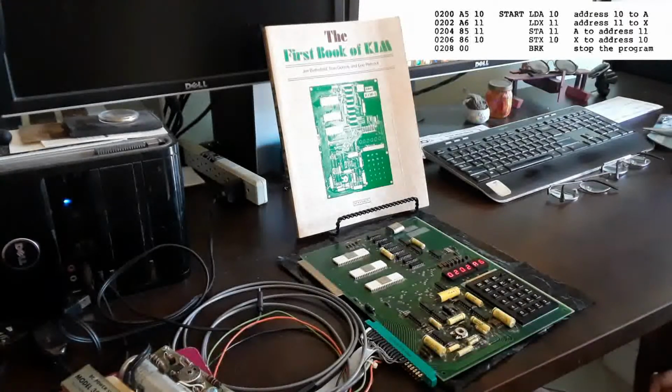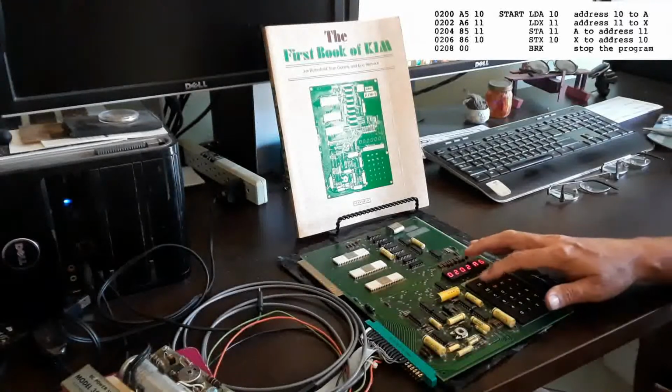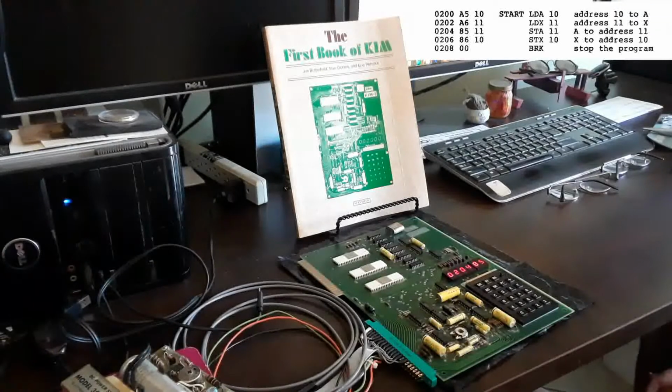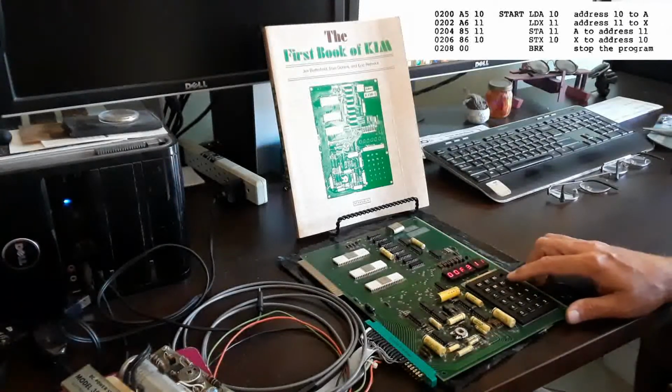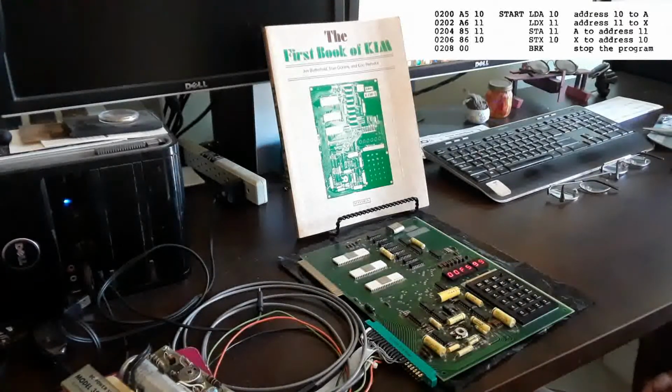Now, if we press go again, the KIM-1 will execute the next command or opcode in our program, which is LDX 11. So our X register should now contain the new value that we stored at address 0011. Again, we can take a look at the contents of the registers by going to address 00F3. First, we can see the A register, then we advance twice to get to 00F5 to see the X register. So this is the A register, this is actually the Y register, and this is the X register where we have our 99. We should see the new value that we loaded into address 0011. Again, we will now press PC to go back into our program where we just left off.